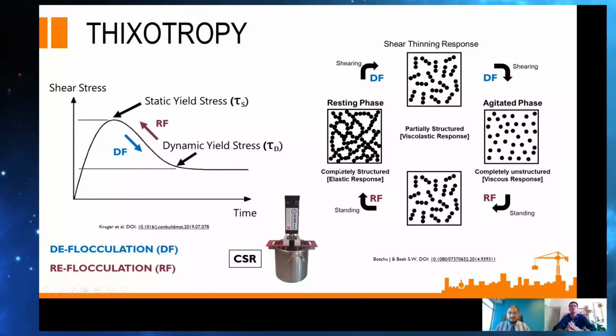So this is essentially the critical material property that we utilize to ensure that we have a concrete mixture that we can pump, but when we deposit this material, it actually has the required amount of stiffness to give you a vertical building capability. Because if you think about it, this is essentially just a zero slump material that we're depositing layer or contour upon contour upon contour.